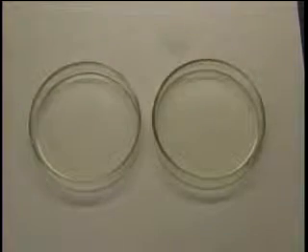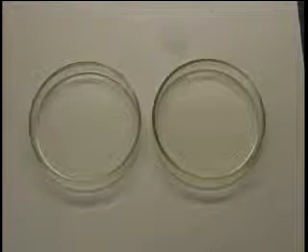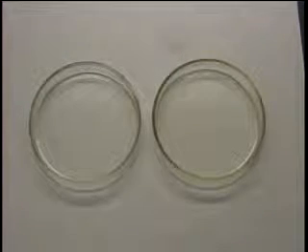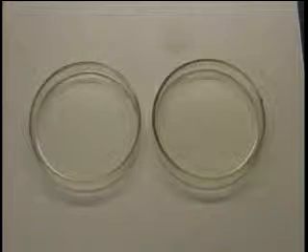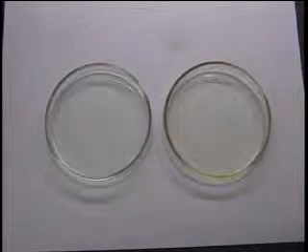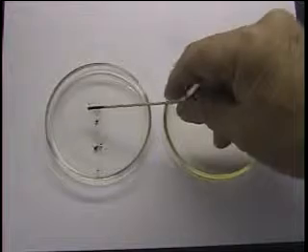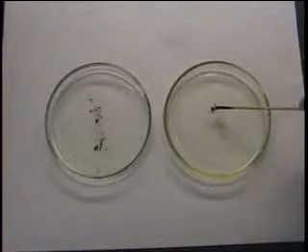Most industrial chains must operate in environments with dirt, dust, and fibers in the air. It's imperative that any chain lubricant have the ability to disperse and suspend any of these materials in order to avoid buildup on the outside, but also the inside of the chain. To demonstrate a lubricant's ability to disperse and suspend dirt and dust, we'll put a very small amount of red iron oxide first into a lightweight petroleum oil, then into a formulated chain lubricant.